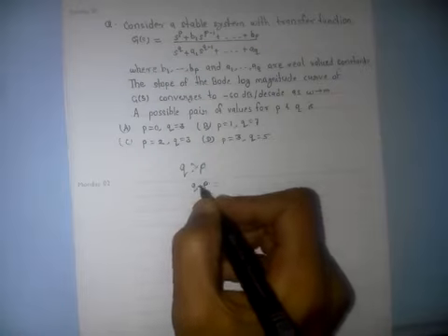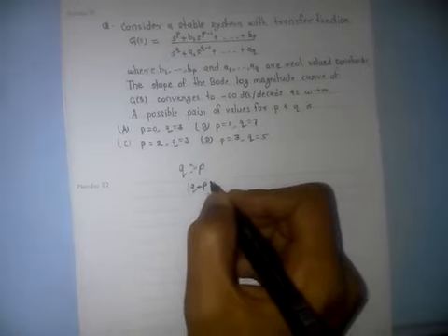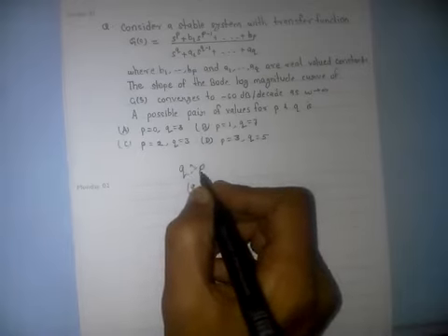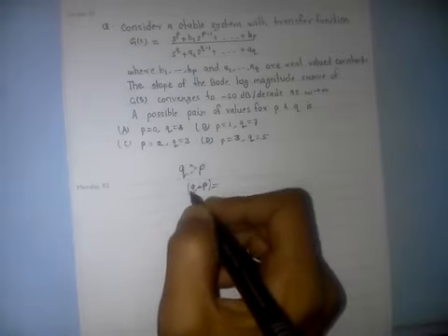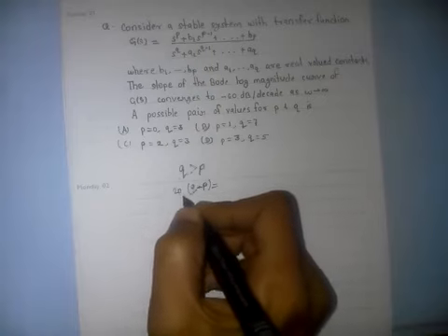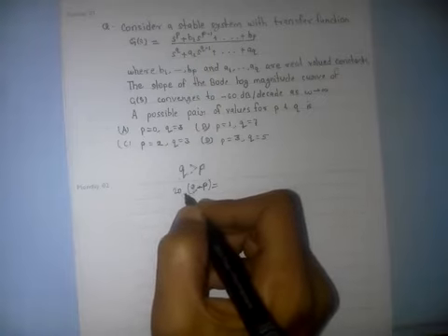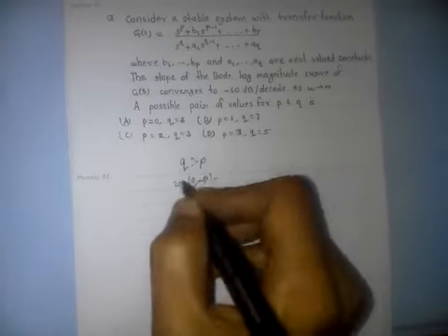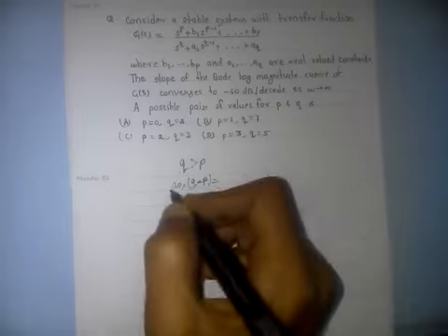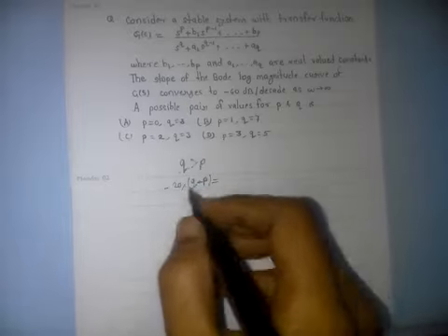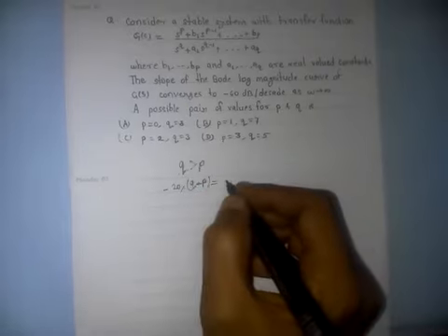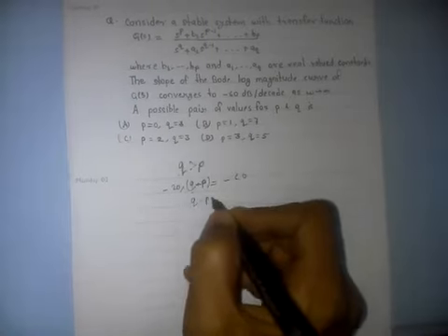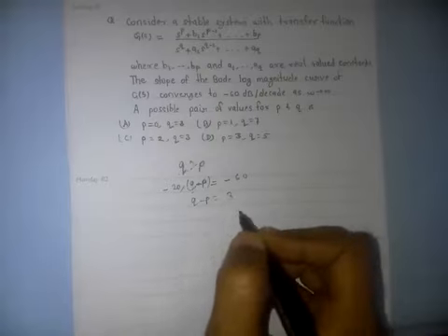The slope is 20 times q minus p, with a minus sign because more poles give a negative slope, and it is minus 60 dB. So q minus p will be equal to 3.